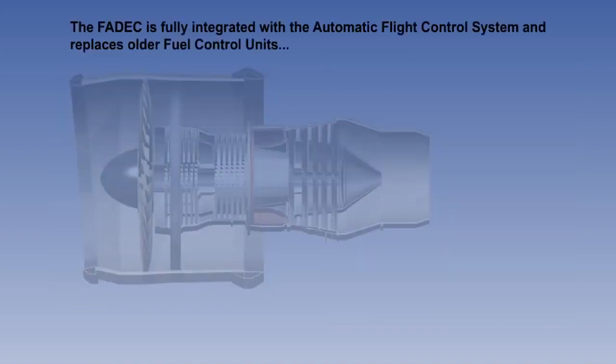Full Authority Digital Engine Control, or FADEC systems, are designed to eliminate the problems associated with the older hydromechanical engine fuel control systems. The FADEC is fully integrated with the automatic flight control system and replaces the older fuel control units, although a fuel pump and metering valve are still required. However, they are controlled electronically to optimize thrust with minimum fuel burn.